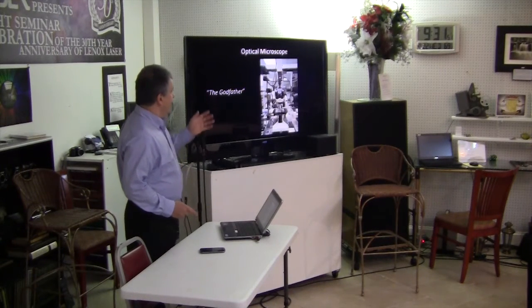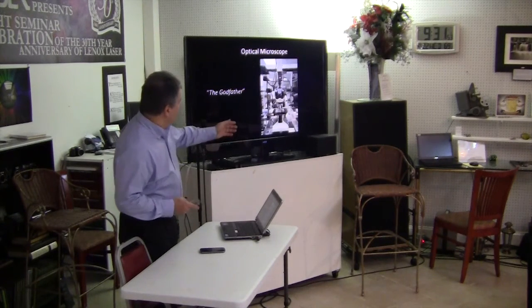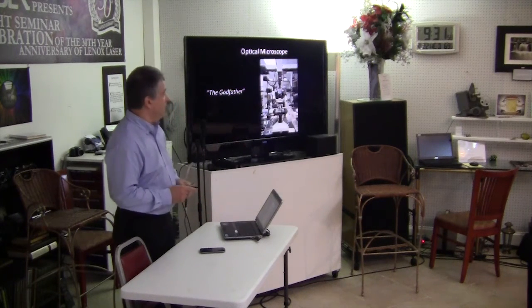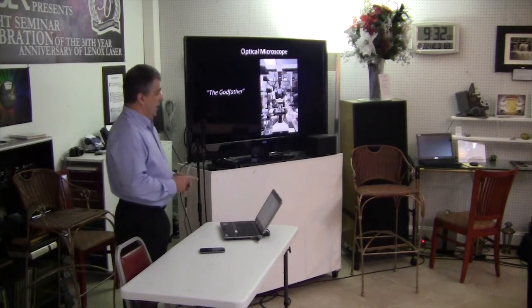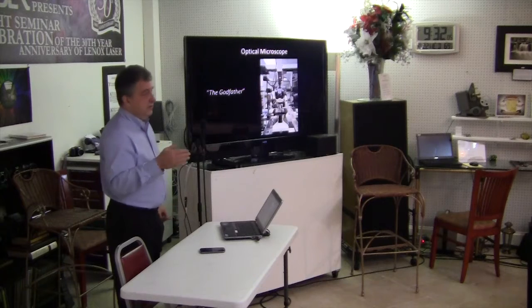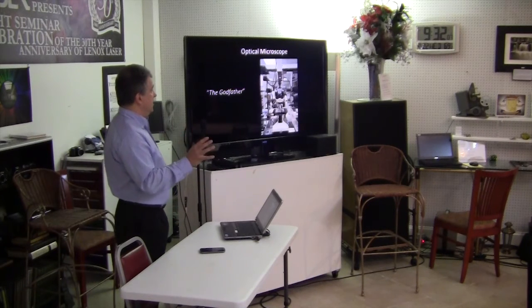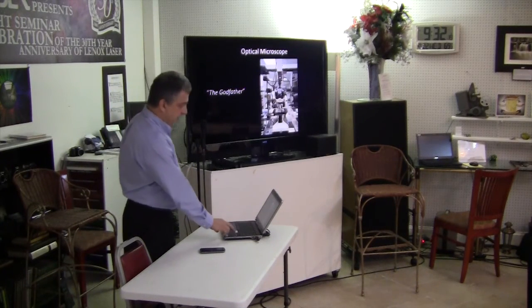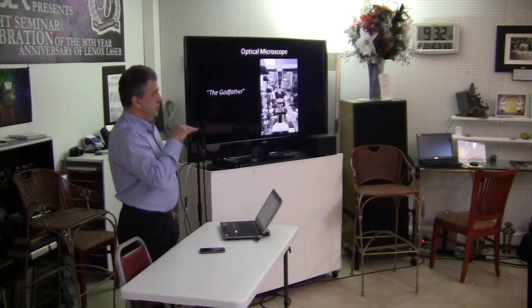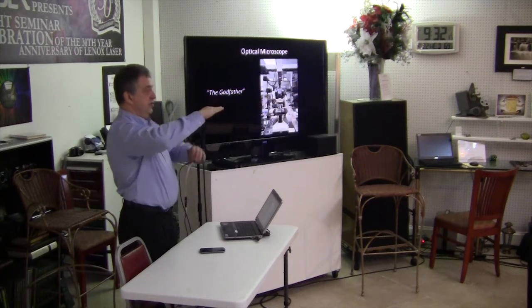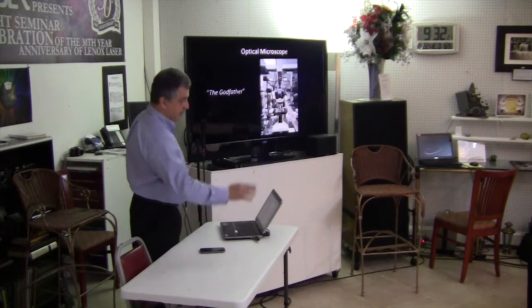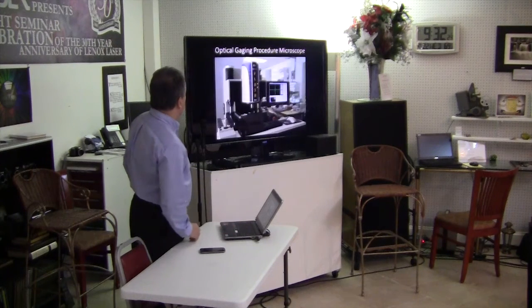The godfather is the regular microscope. It's one of the microscopes that we have on the floor, where you can just look, and at a certain magnification you can see and make a picture of the geometrical shape of the feature that is being drilled. And by changing the focus, you can also go in depth and generate the profile of that.